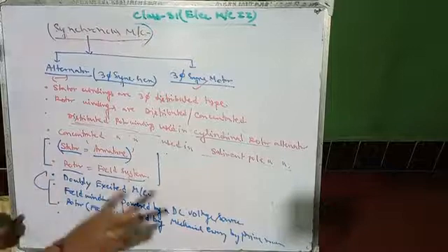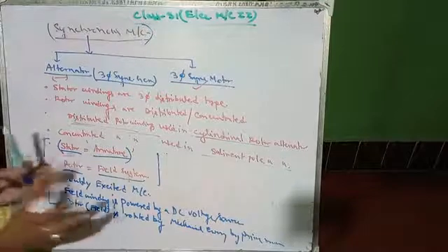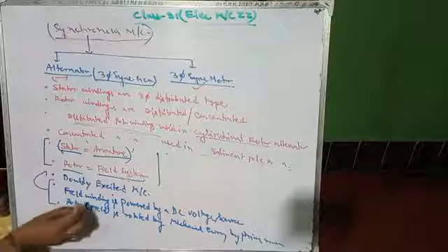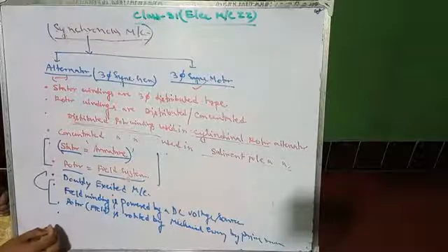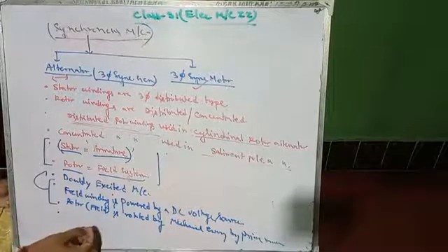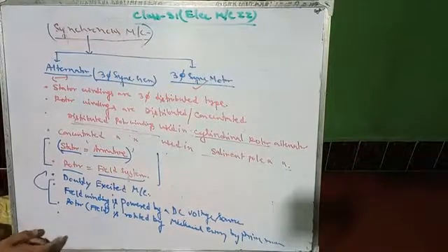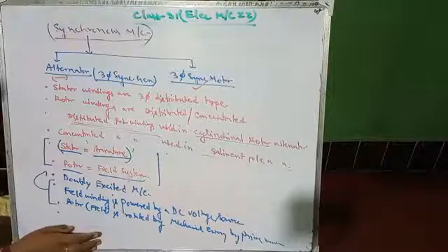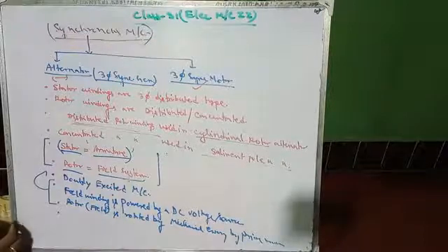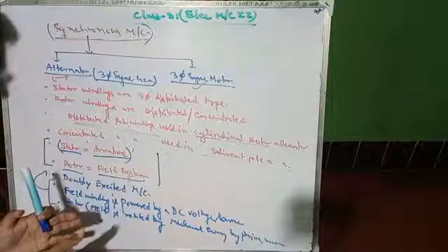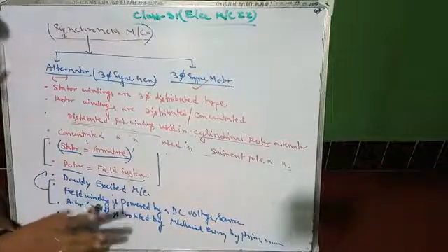That is, there are two possibilities to generate three-phase balanced power. Either the armature winding is stationary and the field system is rotating, or the three-phase armature is rotating and the field system is stationary.